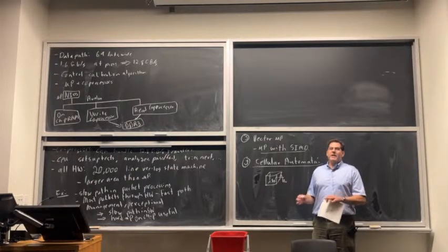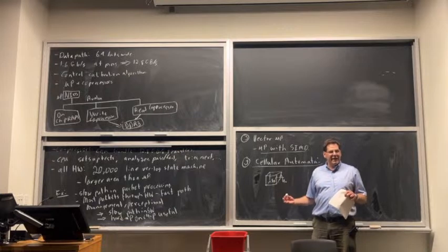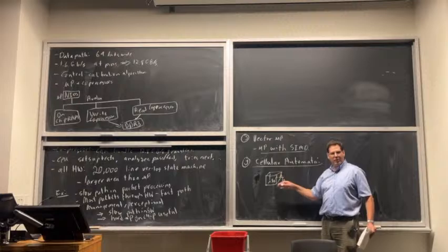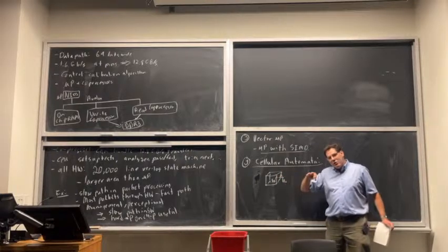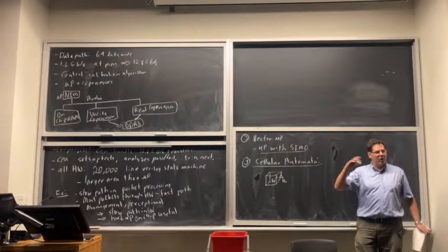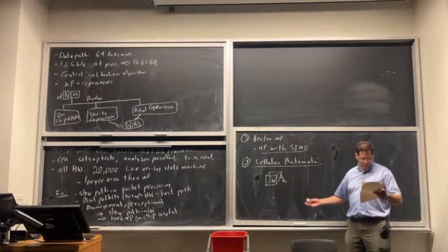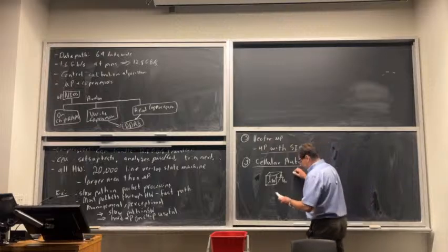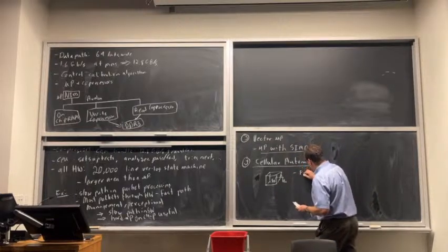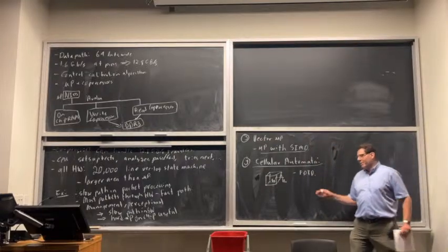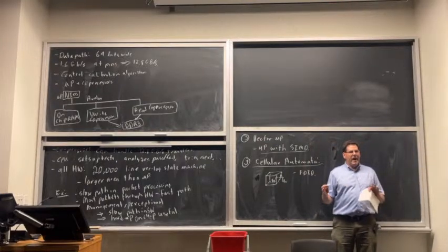For any complicated geometry, you can't ever solve it analytically, so you discretize it. You basically say at all these points, we're going to say what all the fields are, and using Maxwell's equations, we can write all the local update equations. And then we can simulate that in a computer. So what I just wrote down is basically an example of the finite difference time domain, which basically means discretized space and discretized time.